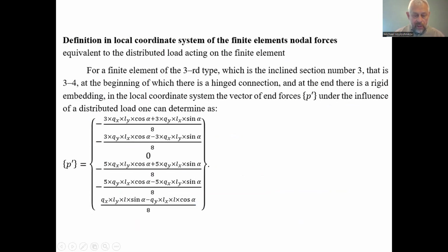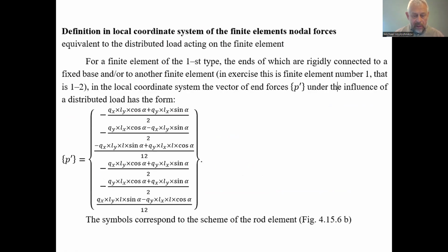So in each of the formulas for the end load under the action of the distributed load for finite elements of all types, for the first type, we just allocated the parts of the formulas which are common for all the formulas, to make the description in Mathcad more compact.